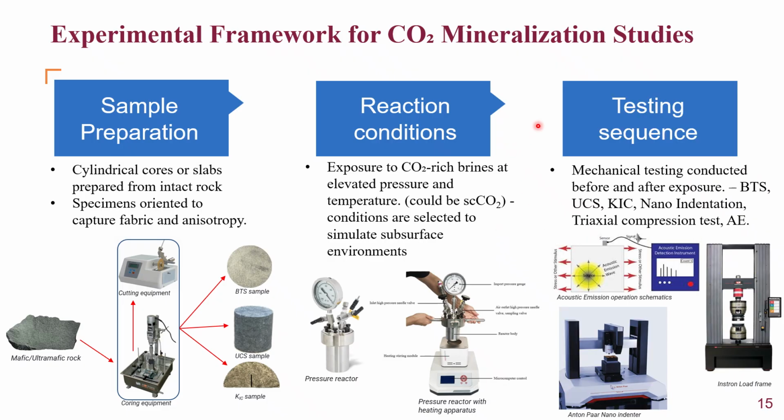Now, in mechanical testing, we could do before and after BTS, UCS, KIC, nano indentation, triaxial compression tests, acoustic emissions, etc. You can see here an Anton Paar nano indentation device, and this is an example of a load frame which has the compression grips, which you could use for your UCS or BTS. And this is the schematic representation of an acoustic emission detection device.